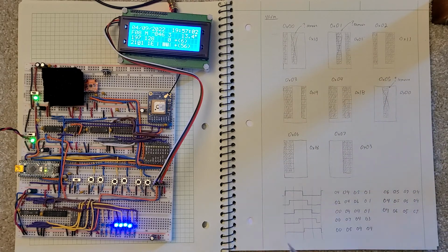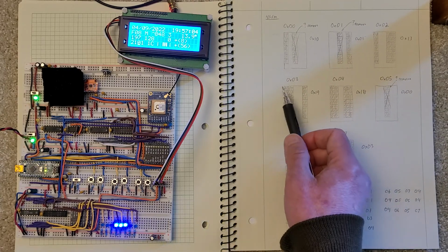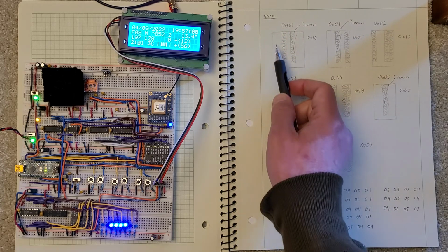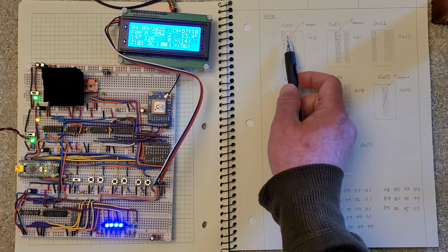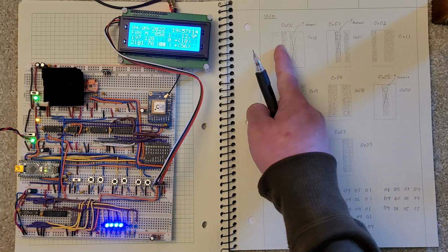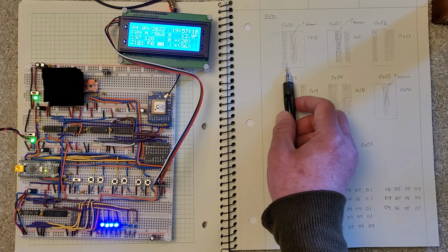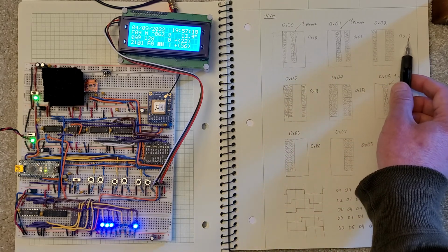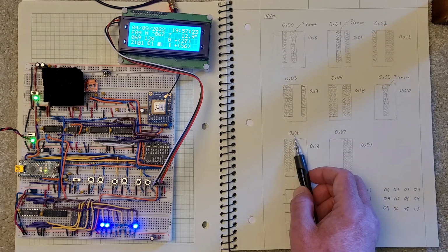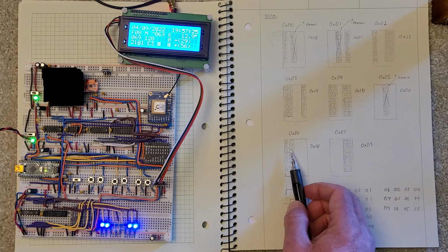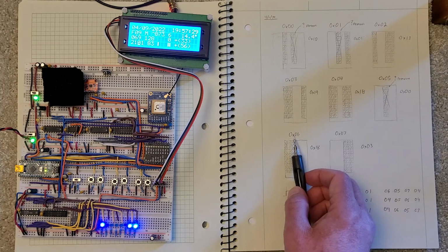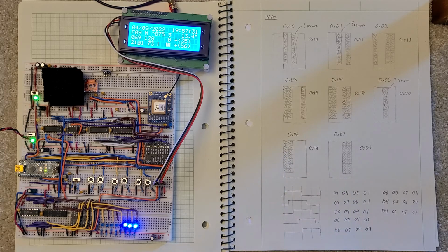And then to actually make the character, you just have to read out the bits. And so since it's an 8x8 array, there's really three zeros here, and then there's the actual character. That's why the character here is a 1 and a 0, because that's 1, that's 0. This is a 1 and a 3, it's a 1, that's a 3. This is a 1 and an 8, because there's the 1, there's the 8, the leading digits are 0.